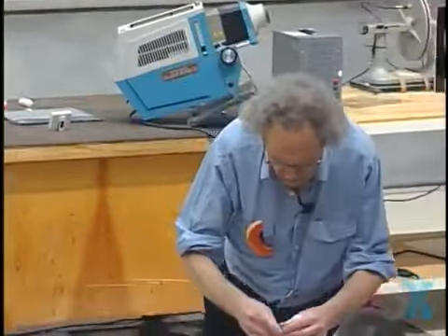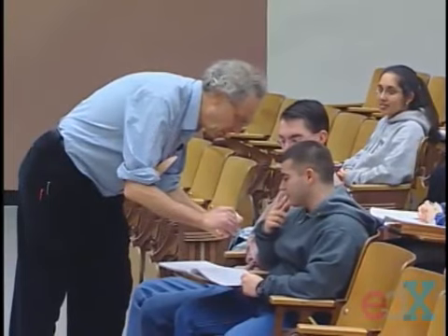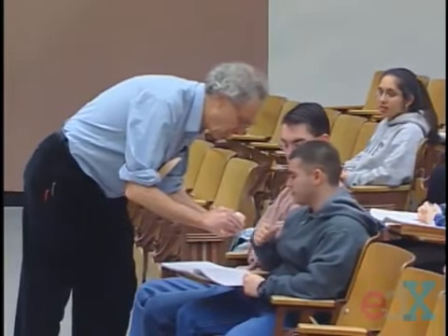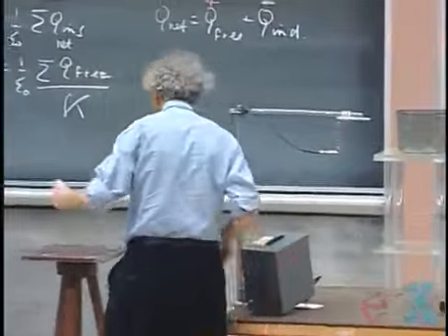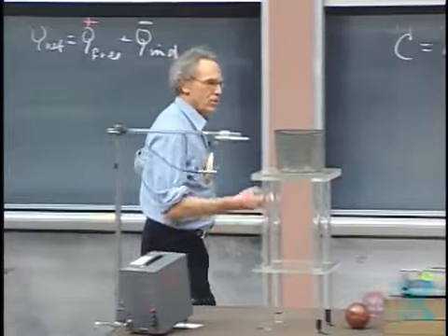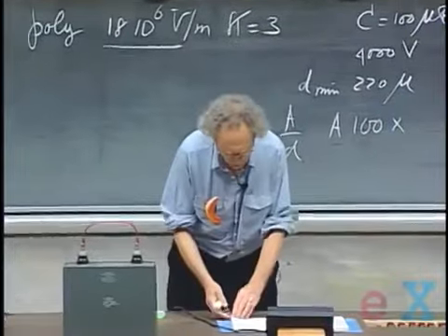Could you tell me what it says here? 100 microfarad, how many volts? 40. 40 volts. That's small. Compared to this one, which can handle 4,000 volts, but the capacitance is the same. So you see now the connection with area and with thickness, by no means trivial.